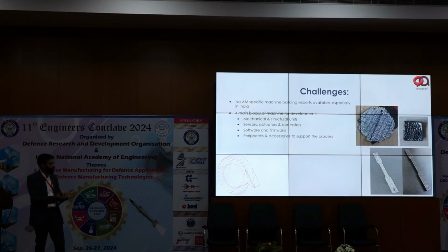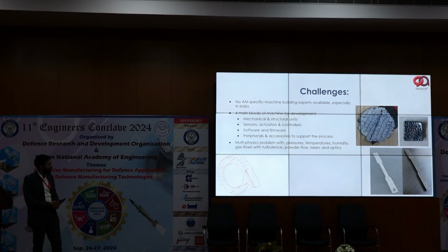We assumed it could be more straightforward, but we had many challenges to overcome, especially when we had to look at sensors and actuators, get them to work together, calibrate some of them, and especially the software aspect of it. We found ways of doing things around that. As I said, multi-physics and gas flows were a key challenge, to get the laminar flow right, just enough to remove the spatters from the whole printing process and not pull out powder, because that's again a very key aspect. Ensuring we get the right laser spots and the optics validated was also a key challenge. Getting the software right for the whole solution is not easy.